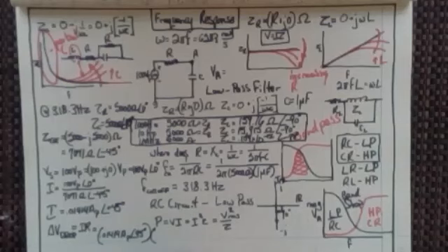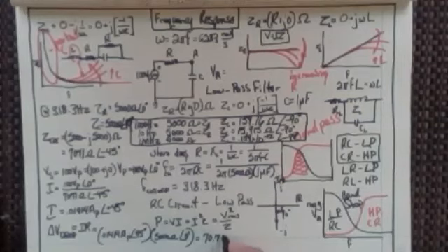And of course, the impedance for that resistor is just going to be 5,000 ohms at an angle of 0 degrees. So what we see, once we multiply these two things together, is we get 70.71 volts at an angle, let's add them, 45 plus 0 gives me 45 degrees, doesn't it? So 70.71 volts at 45 degrees.